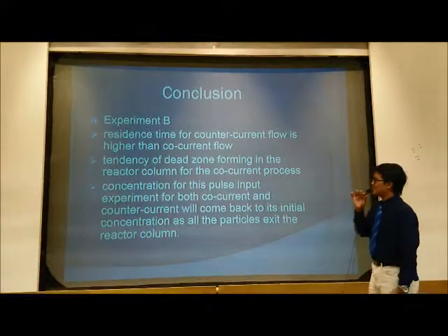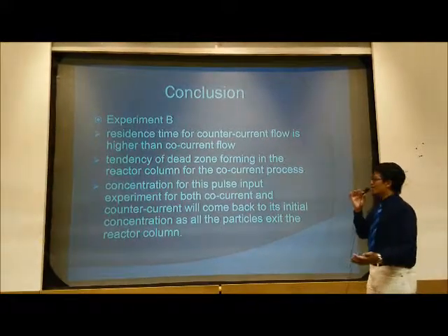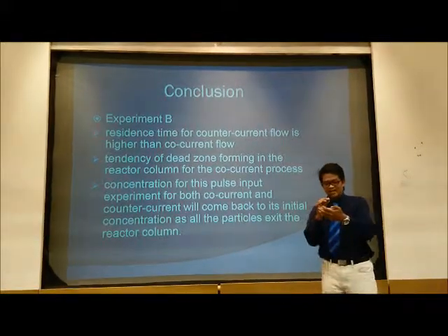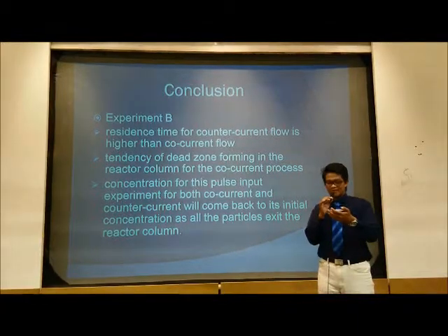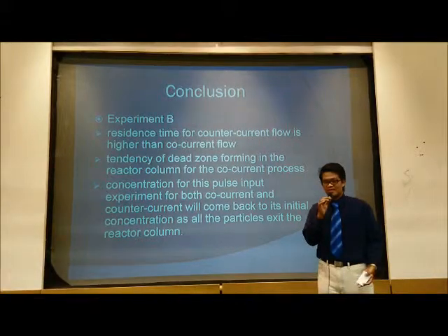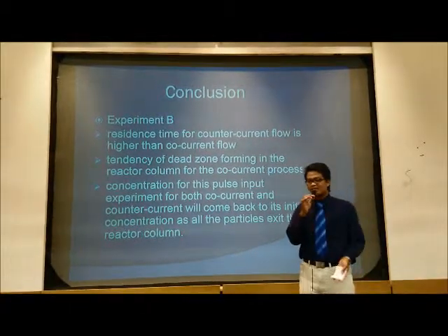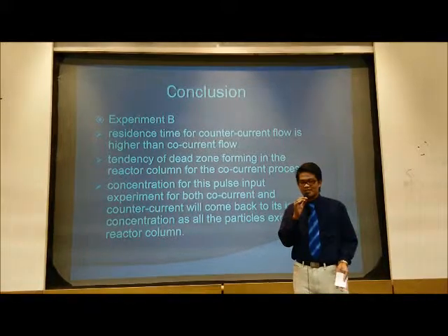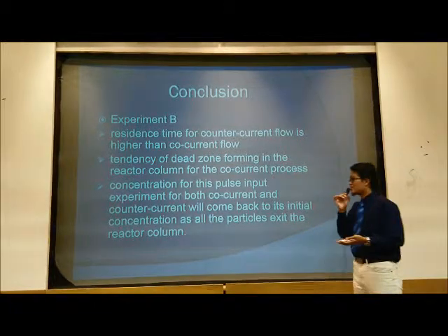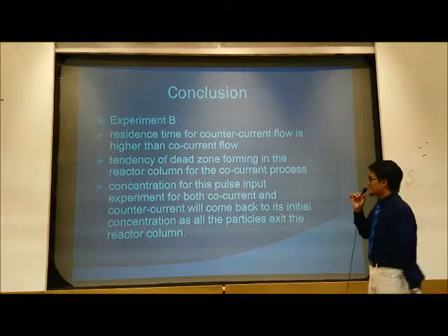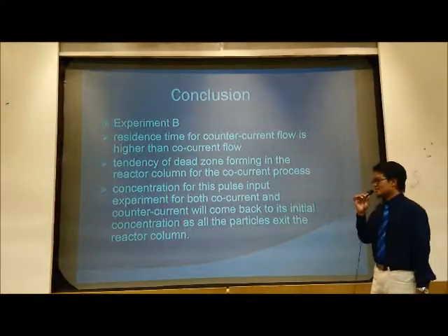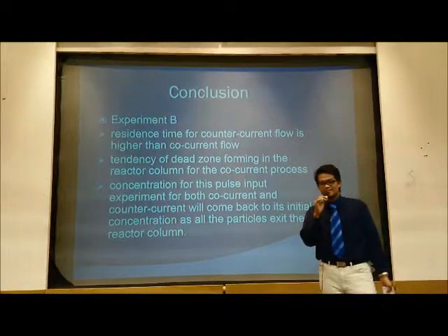And for our second point, there's a tendency of dead zones forming in the reactor column for the co-current process. And why does this happen? Actually, sodium chloride particles tend to flow in lower concentration, lower resistance paths inside the reactor column. And this causes non-uniform particle distribution inside the reactor that causes dead zones to form. And for the last point, the concentration for this pulse input experiment for both co-current and counter-current will come back to its initial concentration as all the particles exit the reactor column.